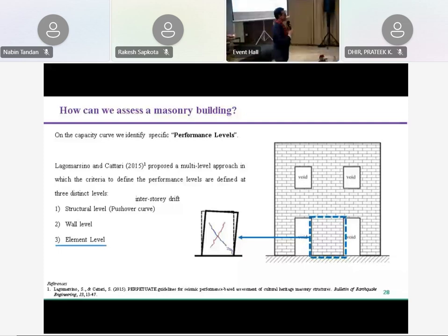So why I think it's important to remark these aspects. So when the regulations that I'm following ask me to monitor a specific element, a specific pier of the wall, to go through my assessment, the use of a macro element discretization as the one we saw, the discrete macro element of the equivalent frame model, could be very, very helpful. Because if I use a finite element method, I will receive a local information.